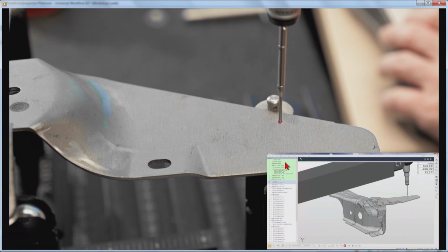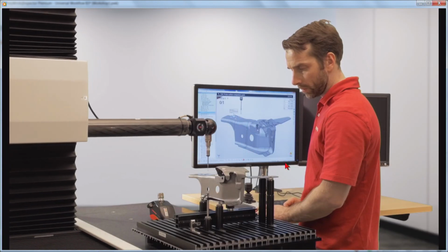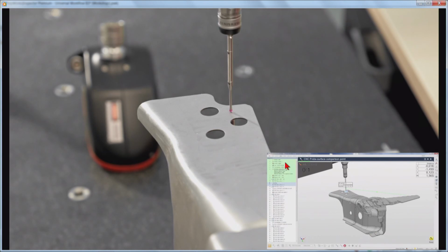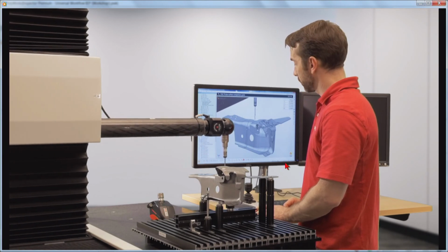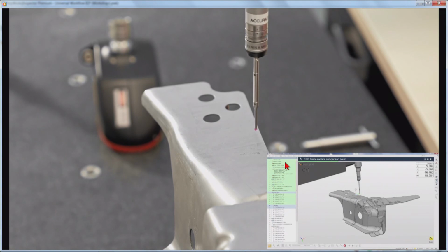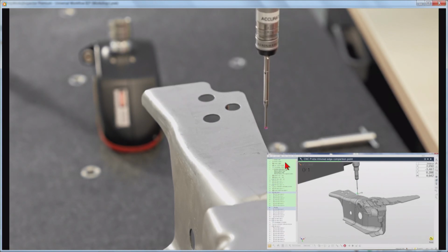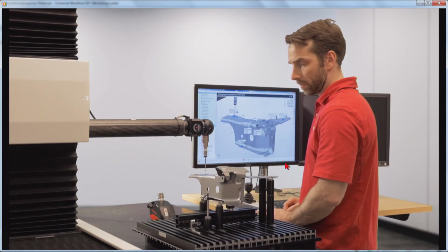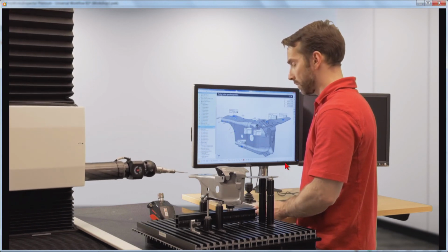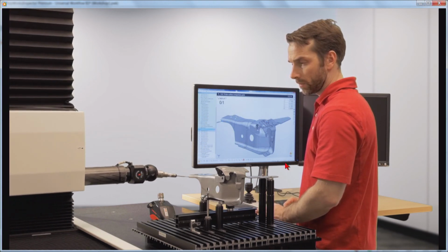So that's our first point. Second point, and then we will measure the two-way hole that we need. Once this is completed, the alignment is performed, we can continue with the measurement. And you can see the adjustment of the sequence took care of making sure the proper tool orientation were applied for the horizontal arm CMM. And you can see it takes the right orientation to continue measuring everything that's on the side.